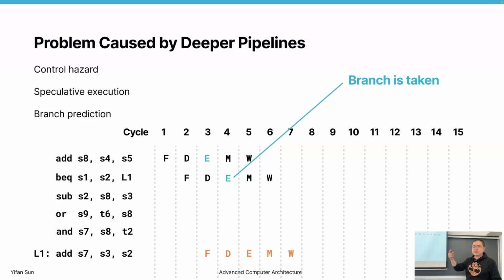So if you have executed this instruction, like taken once, you know where it's jumping back. You can store that address somewhere, right? You can store that address in an extra microarchitecture level register. So you can directly come with fetching this instruction. So we predict it's taken.